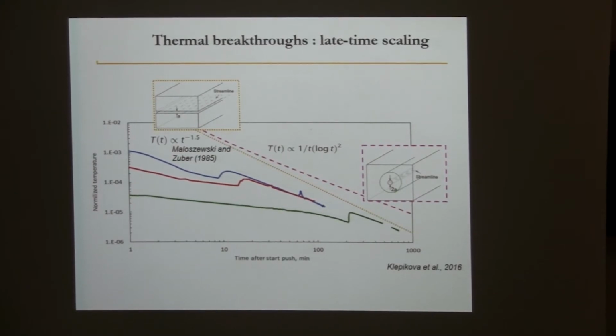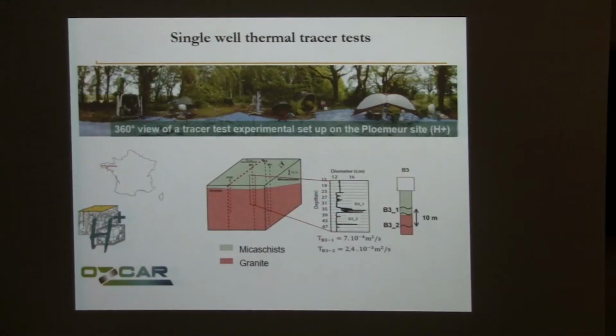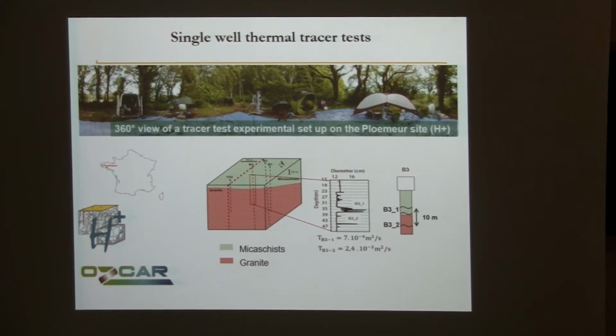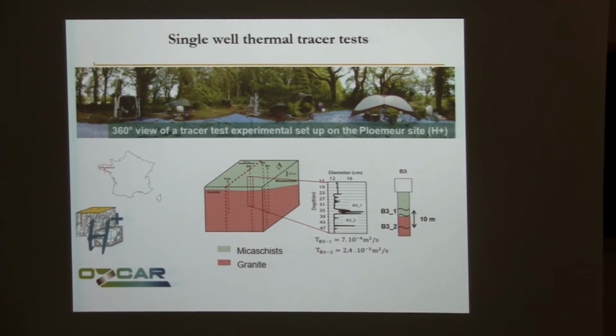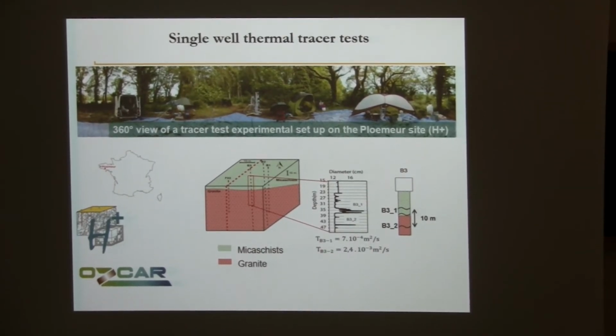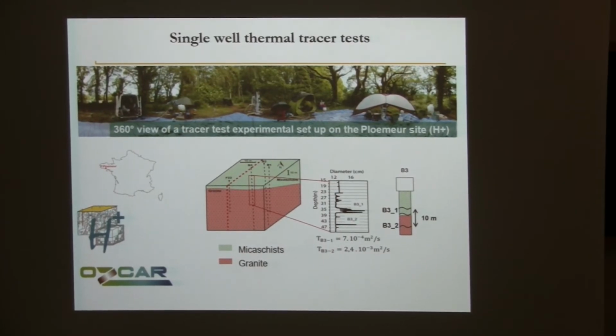So in other words, when you do some push-pull, then you may have some insight about the main geometry of your fracture system, which is either a fracture with the flow dispersed into the medium or a simple channel. We did also some cross-borehole thermal tests. The only thing is that we saw already that sometimes from one borehole to another borehole, it takes days or a few days for heat to travel, because most of the heat you inject will be conducted in the matrix.